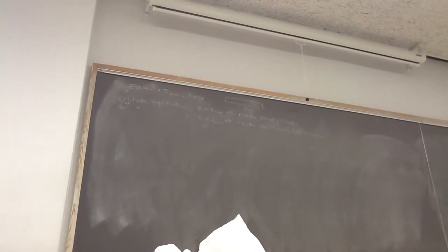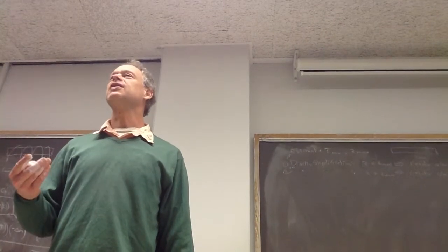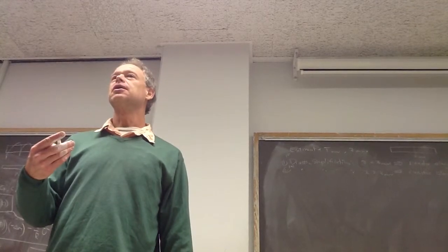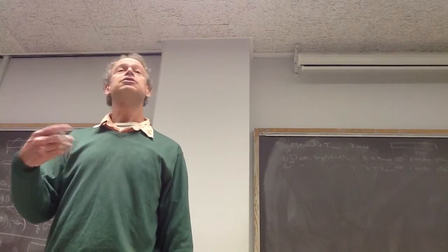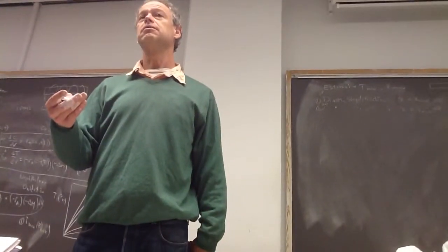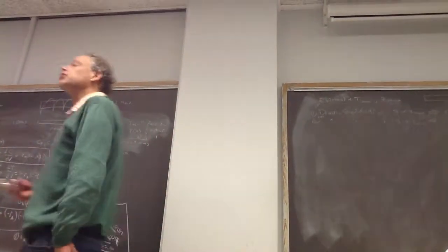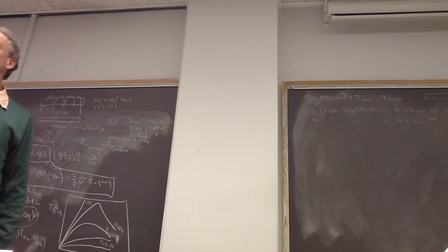Now again, we know these assumptions are wrong. However, in a couple of minutes I'm going to argue to you that these assumptions are conservative. That doesn't mean that they supported Romney. They're conservative, meaning these will give you an overestimate of Tmax. So if you make these assumptions and you calculate a Tmax that's okay, that's not too hot, the real Tmax will be less. So that's an okay assumption to make. It's a conservative assumption. And you can kind of see why that's the case. You can see why this is going to give you a Tmax that's higher than the real one.